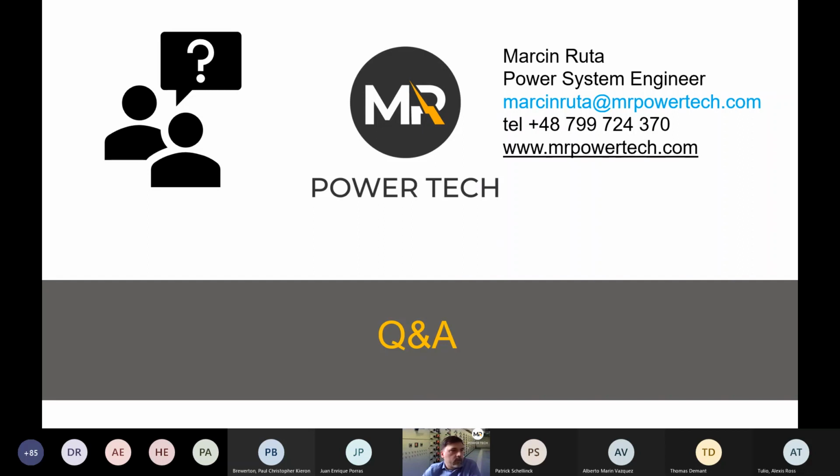Which is accurate to use in an arc flash study: actual fault clearing times, or the 2 seconds arc time per IEEE 1584? First, actual fault clearing time. The 2-second rule is not about the calculation, it's about escape time. So you might use it if you want. For example, if you say we have plenty of room in our substation, and if something happens, we know that this person has a chance to escape.